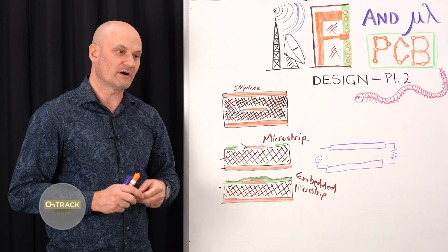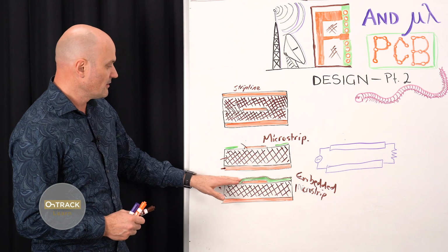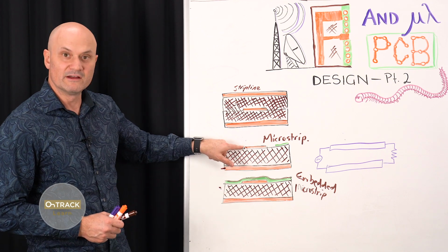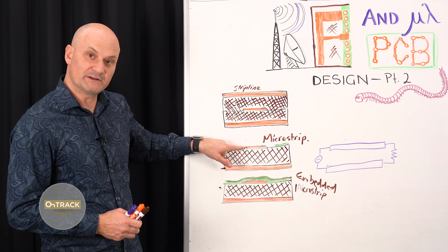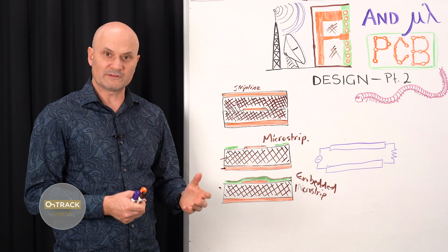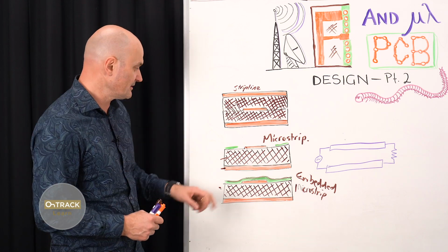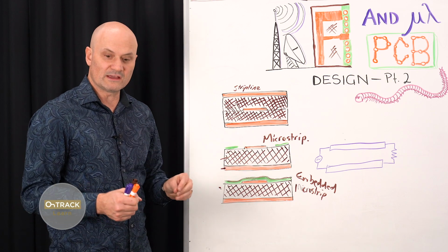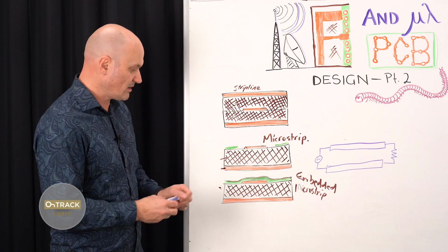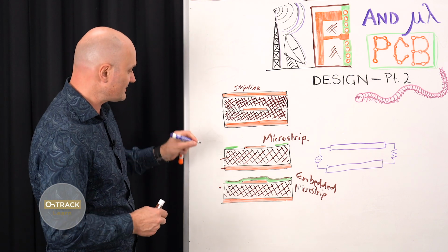And oftentimes for ultra high speed digital boards and for microwave frequency boards, we typically open up the solder mask and have bare or gold or silver plated copper in air. The gold plating preserves it, prevents it from corroding, which would increase the lossiness of the material. And silver does the same thing. It's not used for conductivity. The conductivity is actually taken care of by the copper because, as I mentioned in the last video, we have this thing called the skin effect.